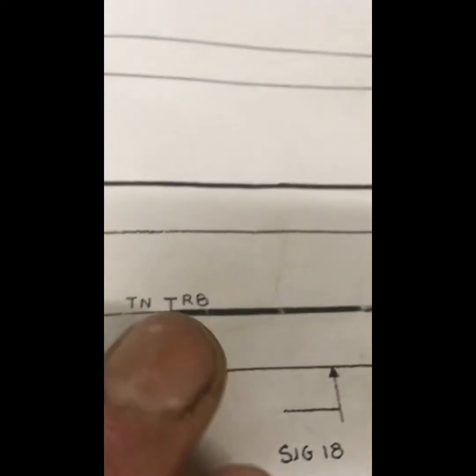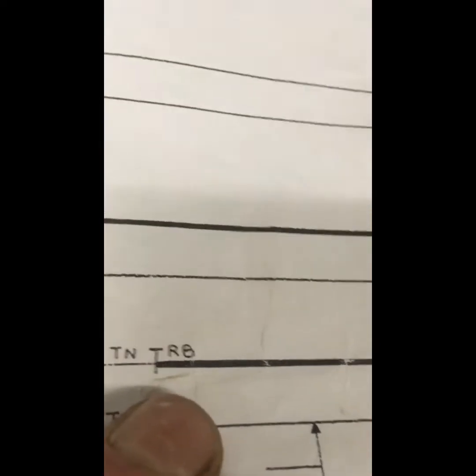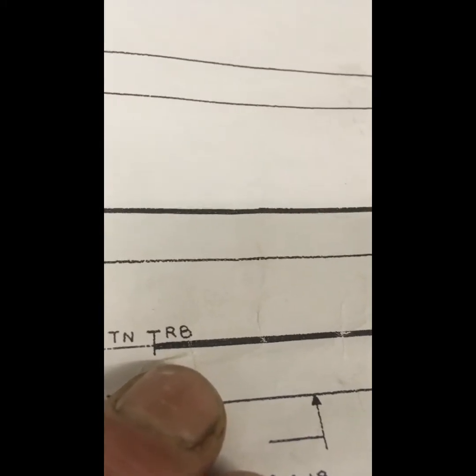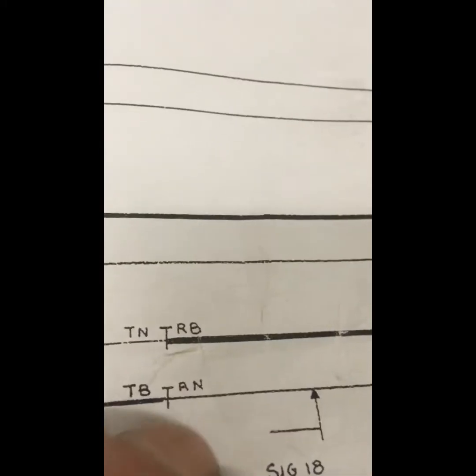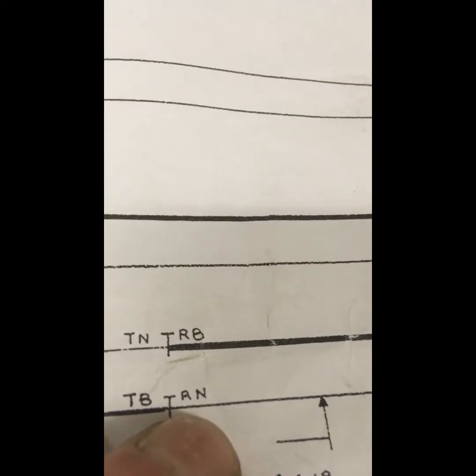One other thing to notice on the bonding diagrams, the positives and negatives are defined differently. So for instance, the positive leg is defined as the thick black line, the negative return as the thin black line, and you can clearly see this here on these two track circuits. And this is quite handy if you're following around the track circuit diagram.